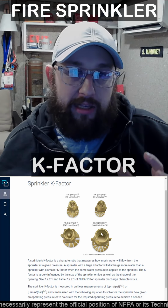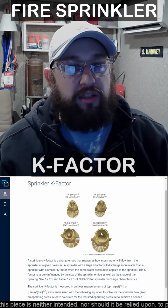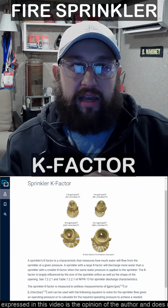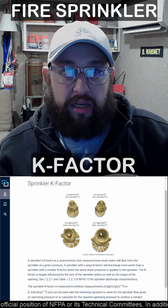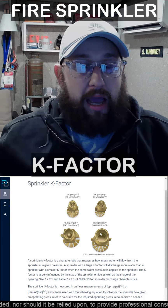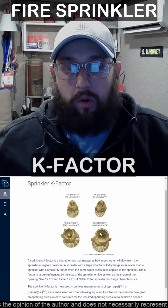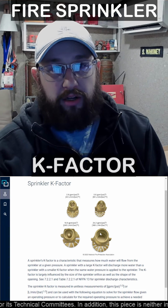Now, if you're not designing a sprinkler system, you're probably not going to be using K factors that much. But I think it's just an important thing to know about that. Not all sprinklers are designed the same. They all might have different orifice sizes, and that orifice size comes into play when we're designing a sprinkler system because we need to design it in a way that we understand how much water is flowing out of the sprinklers. We need to make sure that we have enough water. We need to make sure that we have enough pressure to provide that water in order to control that fire. So that's where that K factor comes into play.